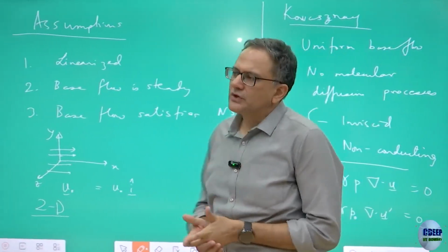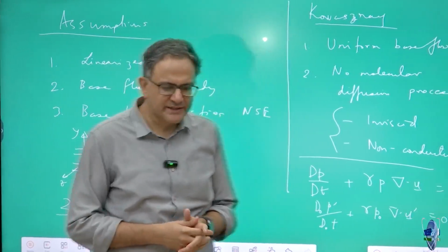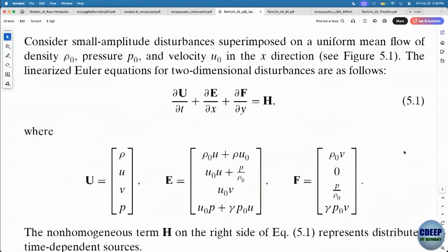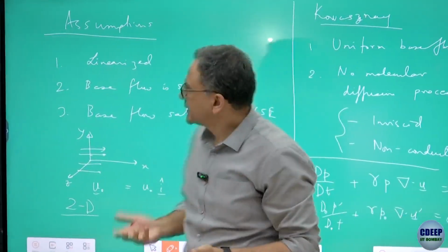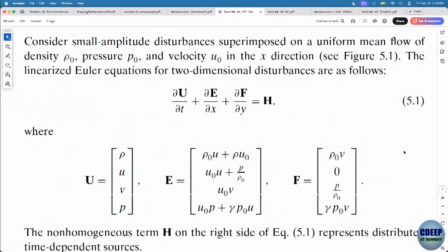So how do you solve this? Given a particular initial condition, that is knowing what is rho, u, v, and p everywhere in your flow domain at t equal to 0, how do you solve this? We already know how to do del del x. Del del y is of course doing this in the vertical direction with the same exact approach. And once we get that, we will take them to the right hand side. That will be our f of u, and we will take the optimized time marching scheme to take it to the next step.